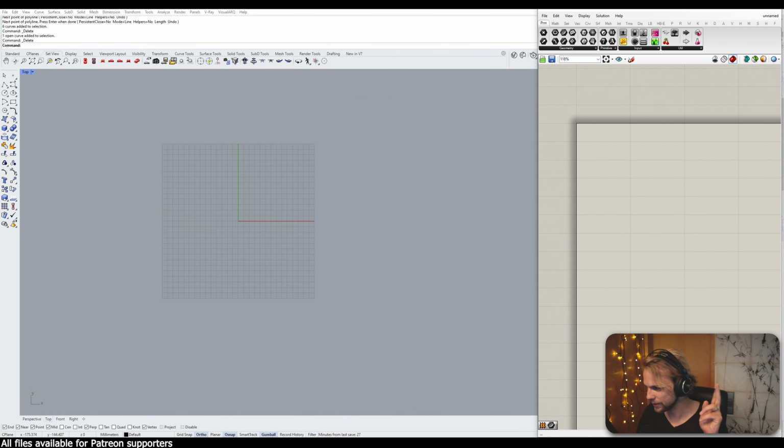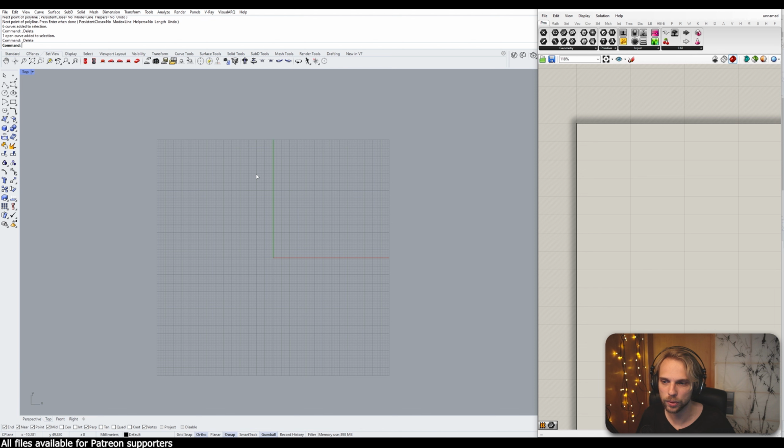All right, let's jump right into it. We are going to be creating a block definition, first of all, of an I-beam, a metal beam that's quite used in the architectural industry, or engineering, I should say. So in the top view, first we need to draw out the cross section of the I-beam, and I'll first create a rectangle. You can just draw a polyline, so you can draw it any way you want. This is the way I do it.